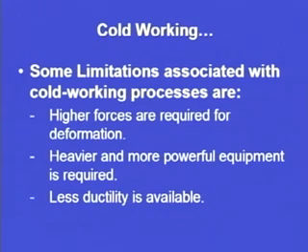So, the equipment or whatever machine we are using for the cold working operation should be very sturdy. It should have resistance to the different types of vibrations that are generated, and it should not break under the applied load. Sometimes there may be some cracks in the bed of the machine.